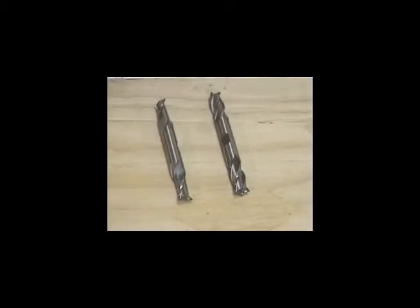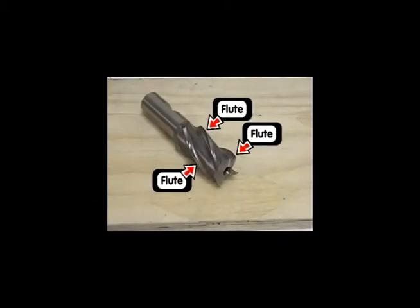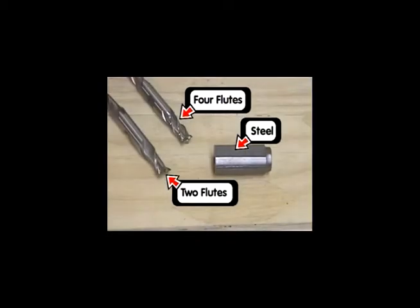End mills have different sizes and shapes for cutting different profiles in the part. The cutting surfaces on end mills are called flutes. The most common end mills have either 2 or 4 flutes. 2-flute end mills are best for cutting aluminum. Steel can be cut with either.